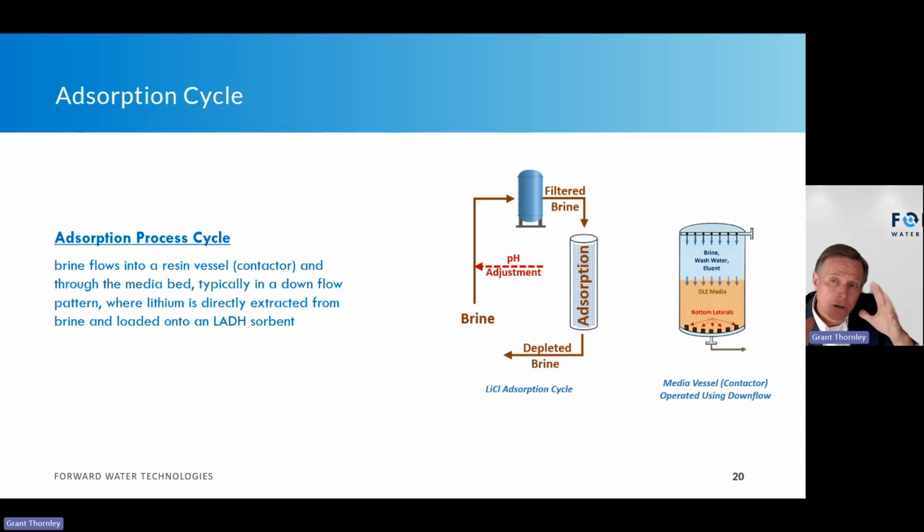Just so you know, the tighter the pore or the tighter the filtration, the higher the operating cost, because the differential pressure or the pressure required to drive that through changes. So that's why you want to do a size distribution, because if I only have to use a multimedia filter, well, that's going to be less expensive to operate than an ultra filter. All depends on what you're trying to achieve. The last thing is that you want to have filtration, because you do not want to be using your media as a filter. I mean, if I got solids coming into this, it's going to deplete the performance of this rapidly. So sorry to belabor that.